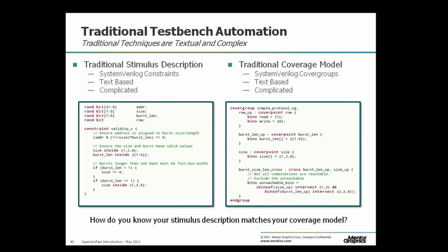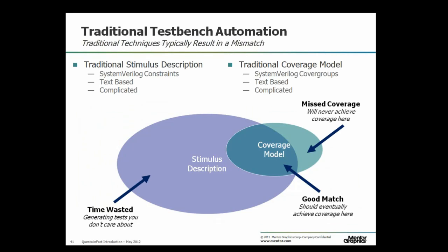So here's a traditional SystemVerilog stimulus description on the left-hand side, and a coverage model on the right-hand side. If you take a look at this, can you tell me, do you know if your stimulus description is matching your coverage model? You get 5 seconds. Right, so we're declaring our address field size, burst length, read and write, describing constraints, setting up a covergroup, coverpoint. So it's complex, and this is actually a very trivial example.